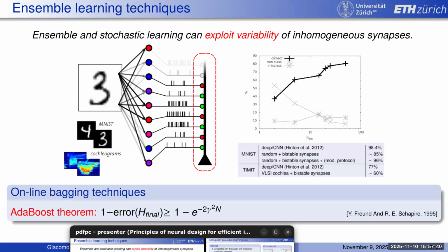Yes, Olivier. Dynamics of the synapses that you have here. The synapses are first order low pass filters. So you have a spike coming in and you have a decaying exponential. And you can change the time constant and you can change the weight of that. They're passive, so they're basically just a capacitor and 2 or 3 transistors.